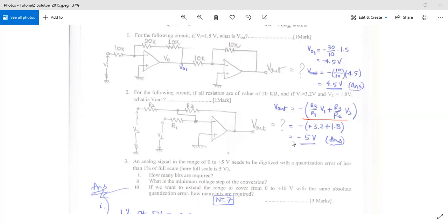Okay. The other way you can read it, remember, like I said, is as two different inverting amplifiers being joined together, right? This one set of amplifier, and this is the other set of inverting amplifier. So these two inverting amplifier voltages will contribute to the total voltage at the output.